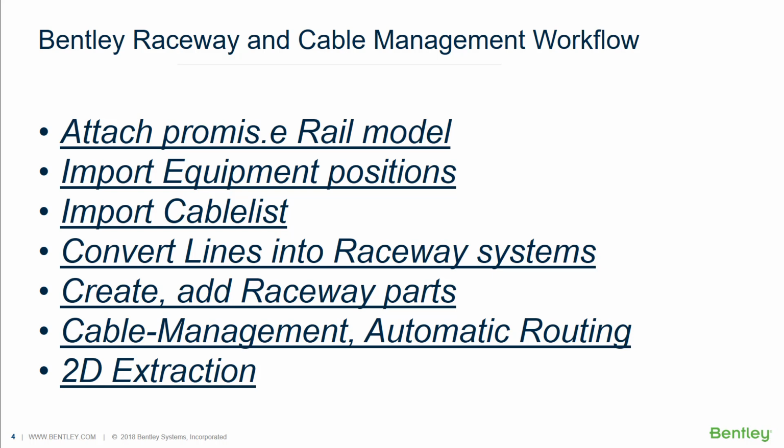In the cable management drawing, later it is possible to do the automatic routing, which will connect the cables automatically from source to target equipment and route them through the possible raceway systems. And as additional output, a 2D extraction is possible, including information and section cut settings with spare information in the raceway parts.